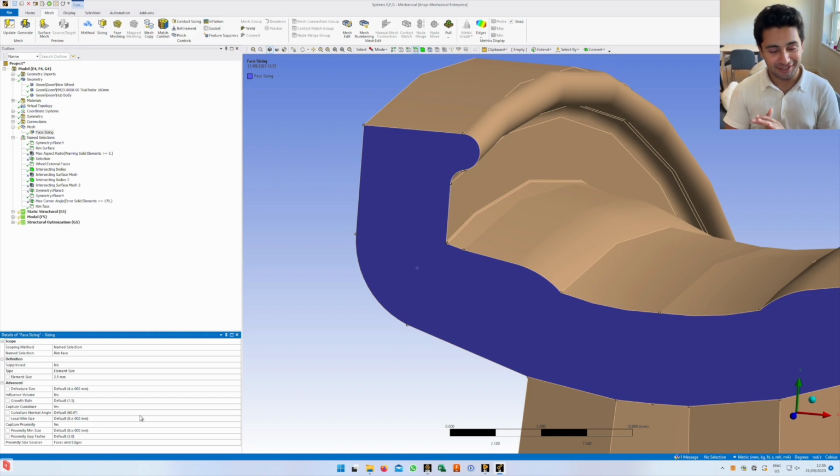And really, there's no one set rule about how to do all of this. Essentially, you have to just play with the options, look at the troubleshooting messages that will inevitably pop up, see what they're suggesting about your model, look at how long it's taking to generate a mesh, and if it's getting caught up on a certain part of the mesh, that may highlight that you're doing something inefficient in a certain area.